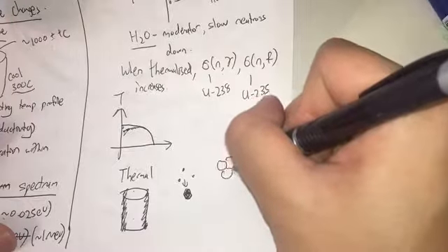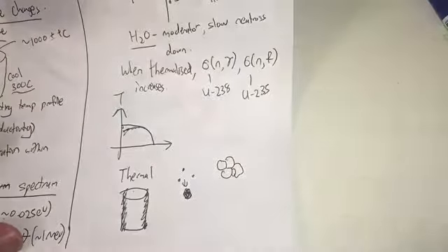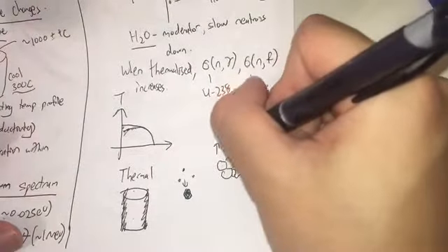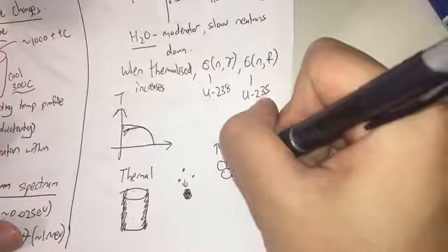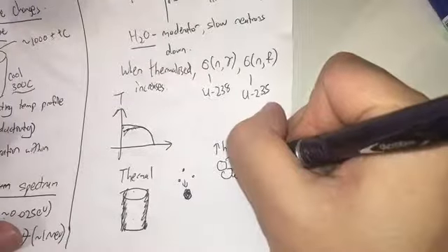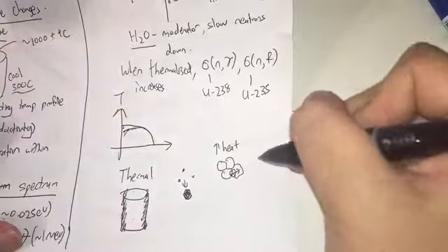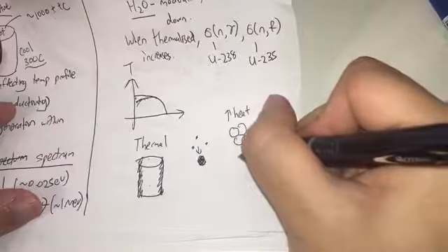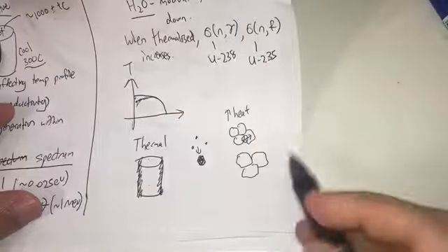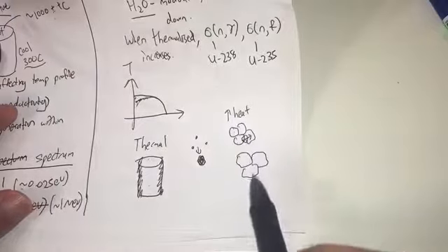So in the fuel we have many grains, some big and some small. So when there's heat, okay, the fuel experiences recrystallization, and the material from the small grains will diffuse into materials with larger grains. So as a result, the larger grains over here will grow bigger, and the smaller grains will shrink.